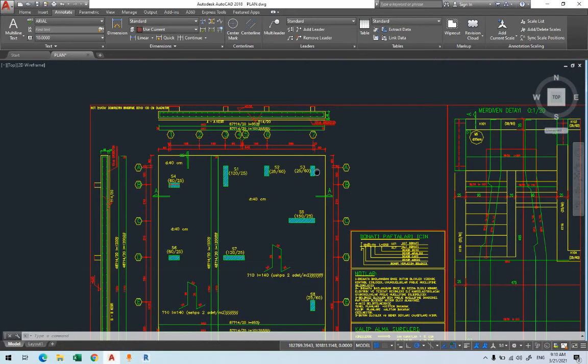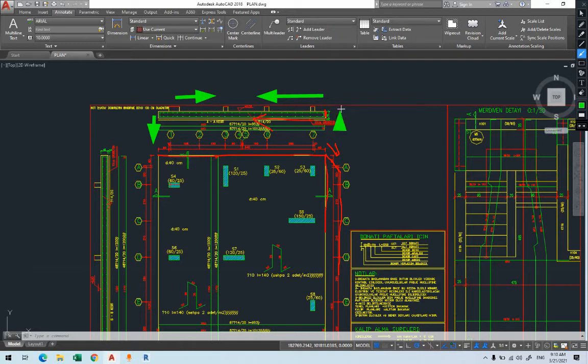For example, if I create the top of the foundation, draw this line, and extrude it down, that's it, I'll get the foundation. I'll extrude it down. Or I can create the edge of it, 40, and extrude it in this direction. That's also possible. So the extrusion works. For example, you do the face and you extrude it in that direction, or extrude it down, or the other way, or you draw the bottom and you extrude up. Whichever you prefer, it's possible, but some of them will be very easy for us to do.